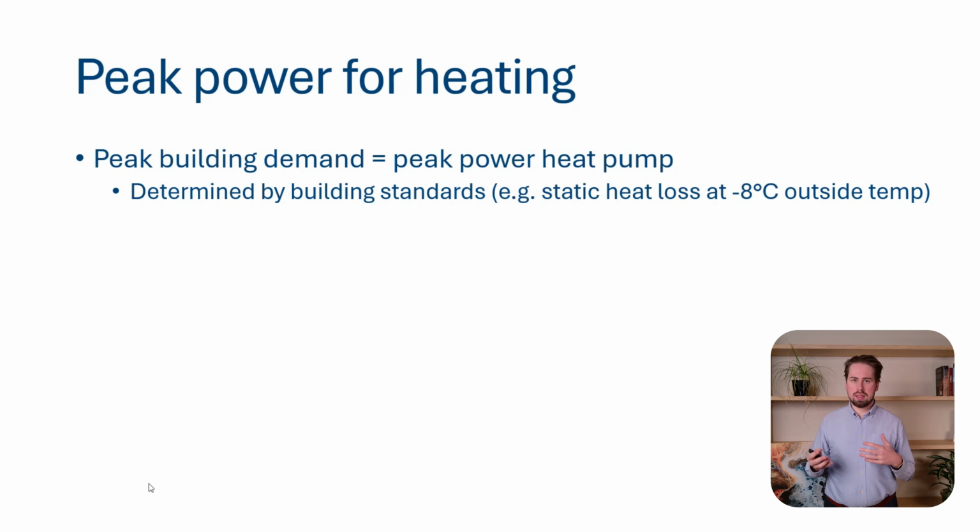And your heat pump is designed according to certain standards that may vary from country to country or region to region. For example, in Belgium, we need to calculate the static heat loss of the building at -8 or -9 degrees outside. And when we have this power, we size our heat pump. And when we know the heat pump, we know the maximum heating demand of the building.